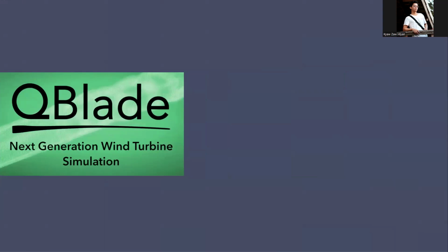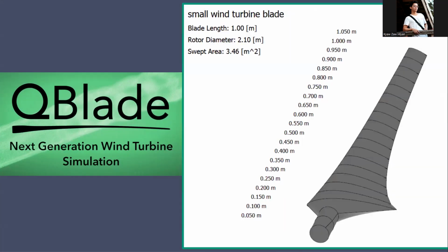So we will use the QBlade wind turbine simulation software, and we finally get the wind turbine as shown here. We will set the wind turbine blades from 0 to 1 meter, and we got a rotor diameter of 2.1 meters and an area of 3.46 meters squared.